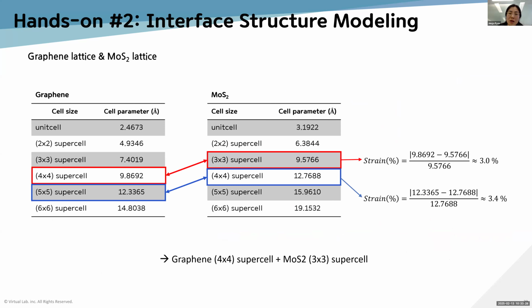There is one important thing to remember when working out the cell size for your calculation. As I said before, the lattice constant values are just examples, based on data provided by the Materials Project database. So we should always use our own calculated lattice constant to make the decision on supercell size. For your own research, you should always calculate the lattice constant first, and then determine the supercell size based on your software, your potential file, and your input parameters.